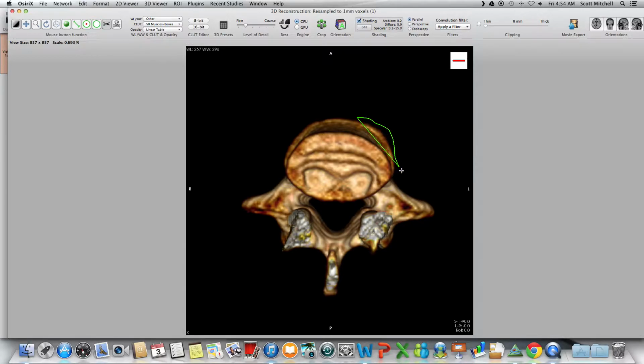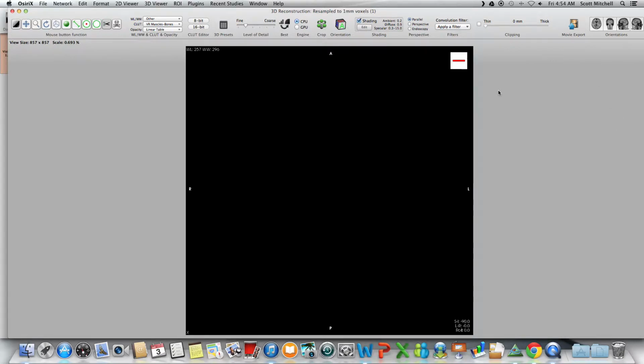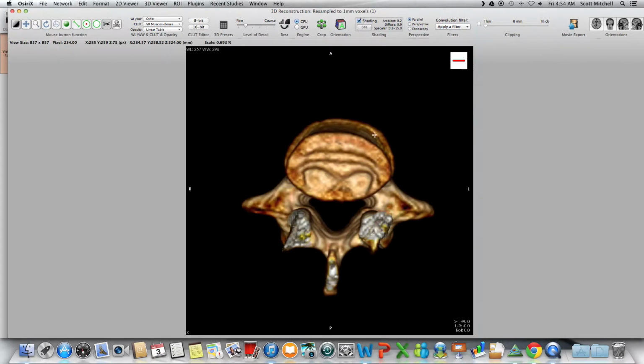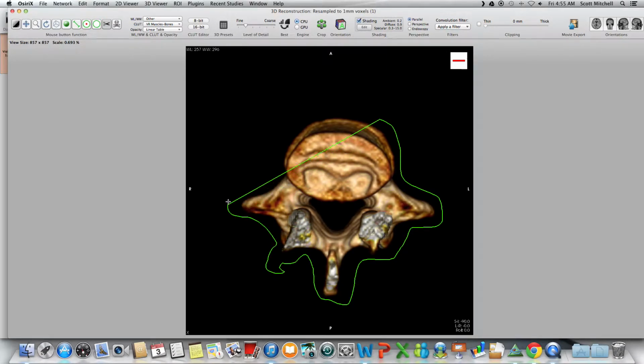So I'm going to just, it doesn't have to be too elaborate because we're going to clean up everything later and it doesn't have that much importance, but I just want to make sure that all the islands out in the middle of nowhere out here, oh shoot, oh, okay, we got it back. Can't multitask apparently. I want to make sure that all islands out here aren't going to interfere with what we're trying to do. So I'm just going to do the lasso again. Instead of hitting delete, oops, hand slipped. Instead of hitting delete, you click enter. That cuts everything outside of here.